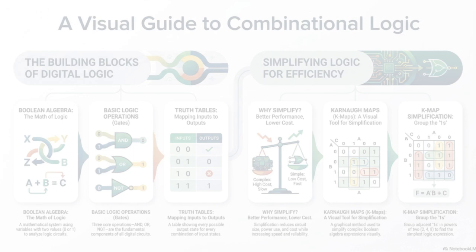And finally, to complete the pair, the reverse of that is the demultiplexer, or DMUX. The DMUX takes a single input stream and connects it to one of several possible output lines. Again, the selection inputs control where the data goes. It's a data router. So that gives us a really comprehensive picture. We've gone from the basic math of Boolean algebra and De Morgan's to the visual strategy of truth tables and K-maps, and finally to these sophisticated pre-built blocks that run modern hardware.